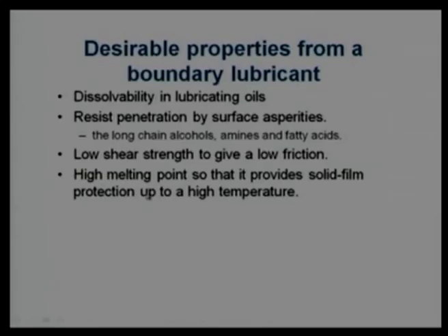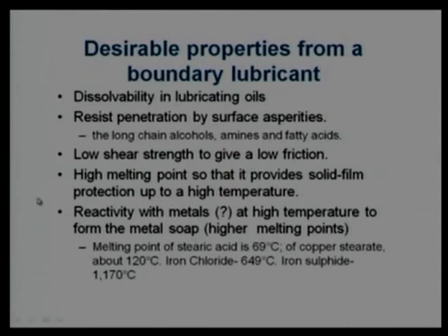So if physical adsorption is able to sustain up to 250 to 300 degrees centigrade, that will be the preferable choice. In that case, we are not going ahead with chemical adsorption, because we know chemical adsorption is going to corrode the surface, lubricant additives will get depleted and we need to replenish the lubricant. And finally, it needs to suit the metal which we are using. Here I say metals, because mostly these kinds of additives are effective with metals. They are much less effective with polymers and ceramics.